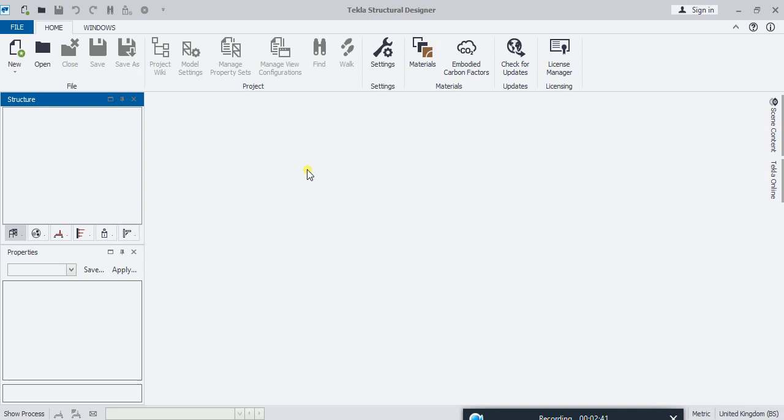The only workaround is to send it to Revit, and then from Revit once again to send it to Tekla, full version. Some mistakes might be appearing, especially if you are having, let's say, not symmetrical arrangements. I'm going to show you how to transfer between the two software, and then the loading as well. In most of the scenarios, when you transfer from Revit to Tekla, the loading will not be fine, so you need to remodel the loading once again.